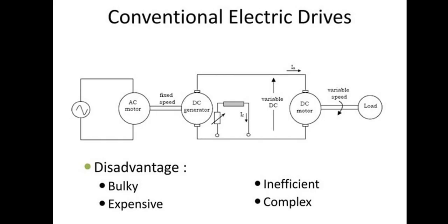As for modern replacement, the Ward Leonard system has been largely replaced by static drive systems. That means thyristor-based DC controlled drives and variable frequency drives for AC motors. These modern systems offer higher efficiency, compactness, and less maintenance.